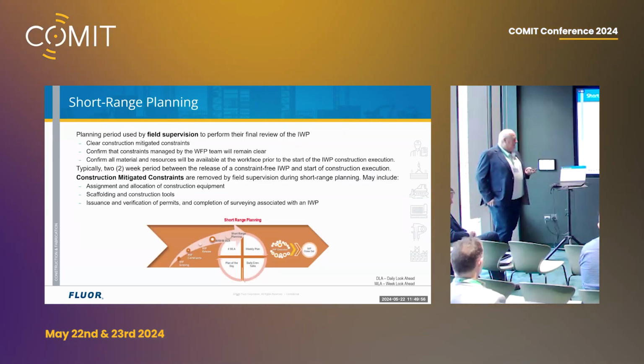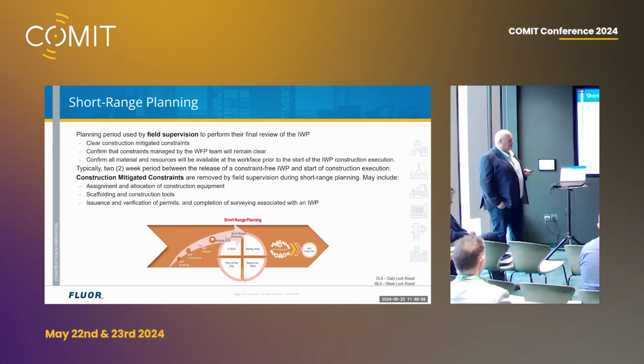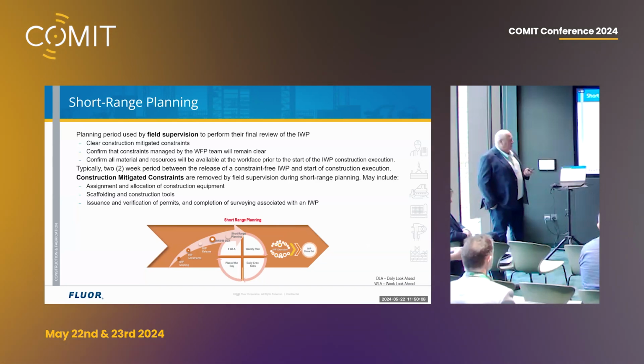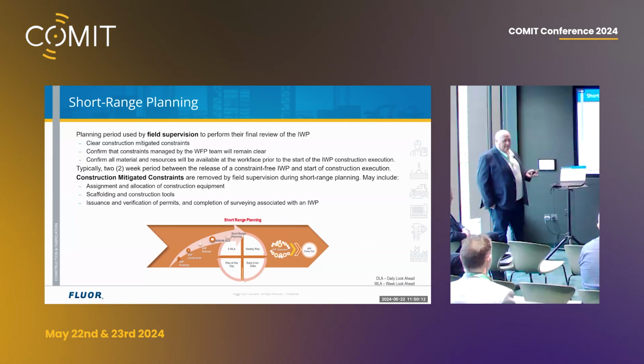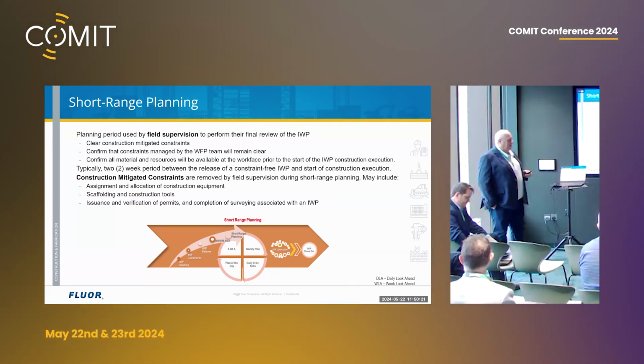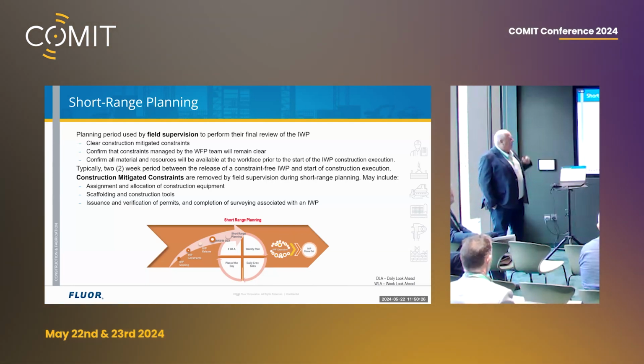Moving to short range planning. So again, IWPs, we're looking at 30, 60, 90-day look aheads. Could be longer, could be shorter, depends on the projects. But it's a look ahead of what's happening. Most projects, smaller ones, will use P6 for this. Other projects don't want to overload it with that amount of data. Then it starts driving into a 4-week look ahead, the weekly plan, the plan of the day, or what the crew tasks actually are. But it helps mitigate any other problems there might be.